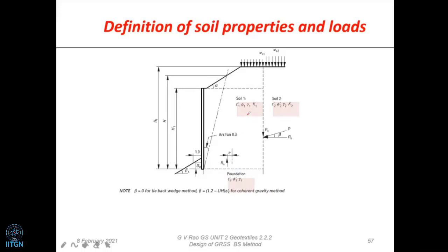What you are going to pick up, usually it will be cohesionless soil, that means granular soil. And C is not there, but C could be there in some rare cases. But anyway, it could be having C also, but otherwise this is not done normally. The most common kind of soil which you are going to pick up is going to be granular only. Okay, so then the design height we already got based upon the figures which you got now.